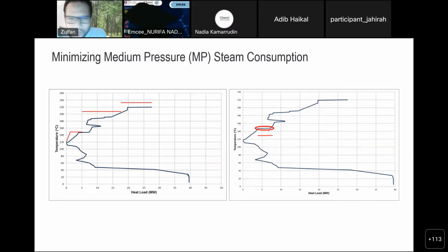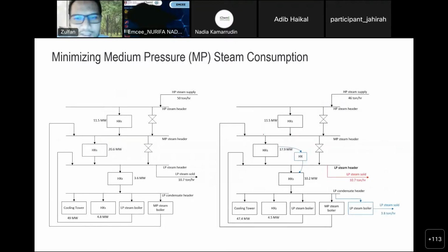So we think to ourselves, okay, can we do something about this, because this is very close to the pinch point? Can we change this from these locations to a little bit below the pinch point? Yeah, like 30 degrees C. It's not that small, but it's quite something. In the end, we did change that. So we changed the column pressure in such a way that it no longer needs the medium pressure. It needs the low pressure header. So from here we move it down to here. In this case, we reduce the amount of energy, which translates into some reduction in the amount of money.